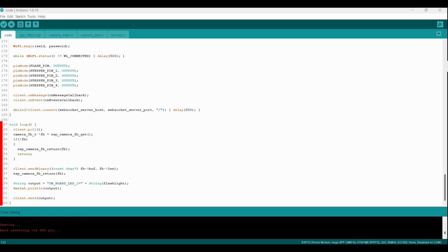In the Arduino lifecycle, both the setup function and loop function are required. The loop function runs continuously once the setup function completes its execution. It is responsible for the main logic of the program, and it runs over and over until the Arduino is powered off or reset, and is considered the heartbeat of the Arduino program. So the loop function is responsible for performing any tasks that need to be repeated over and over, such as reading sensors, updating outputs, and checking for input events.